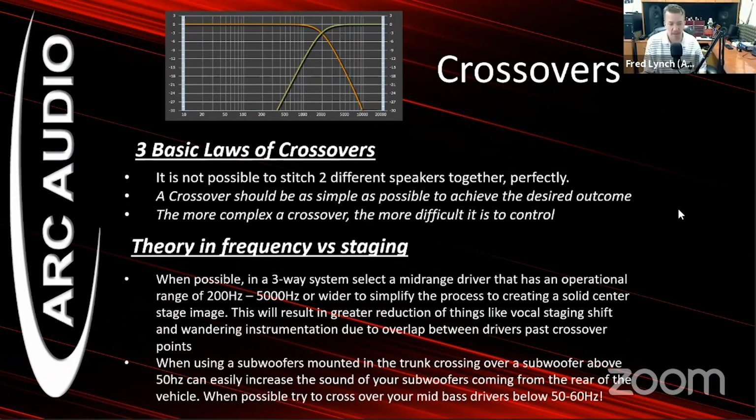Having multiple speakers in different locations or having a crossover point in the middle of that 200 hertz to 5K range can definitely increase the complexity of the system. And it could also greatly increase the complexity of how it gets tuned, resulting in things like vocal staging shift, where a singer gets louder and you hear her move from one spot to the next, or the frequency starts causing instruments and vocals to wander all over the system versus sounding like you're at that live performance.